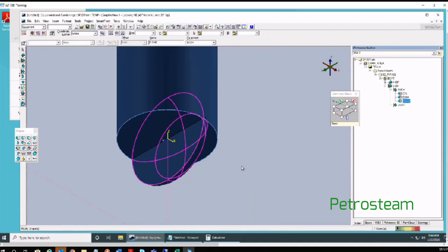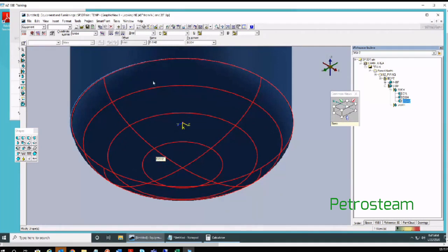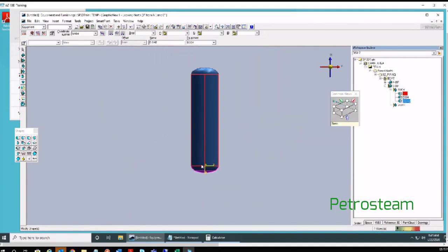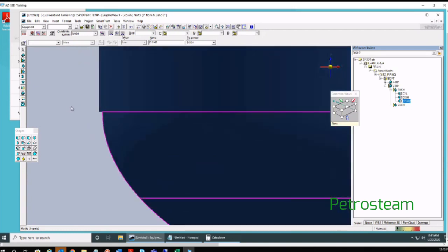If I have to rotate down, I will use left arrow mark. With left arrow mark, it rotated down, and then it is as required for us. Okay. So just check in the front view whether it came properly for your cylinder. So this is your bottom cylinder dish and you have placed it to the cylinder.